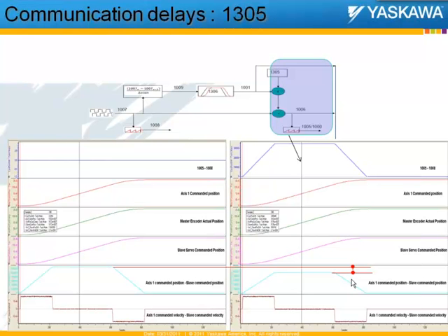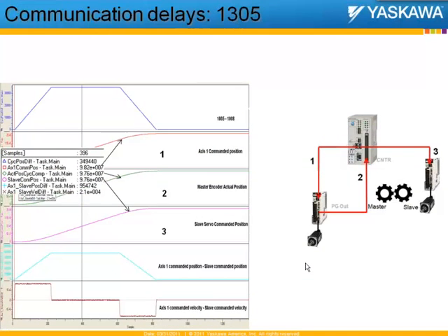You can see that the difference between the master and the slave has already come down. An expanded view of that compensated position: if you remember from an earlier slide, the external encoder position that it was reporting was 9.72e7, but with the compensation used on the external encoder position, that position is now 9.76. So you can see that the slave is now commanded to 9.76 instead of 9.72, which was the number without compensation.